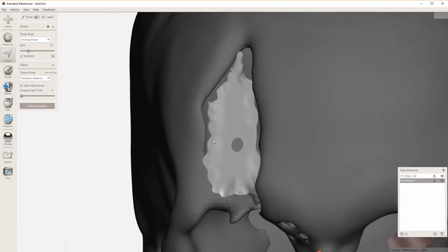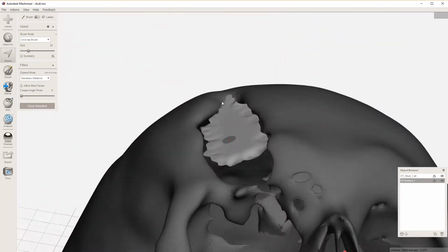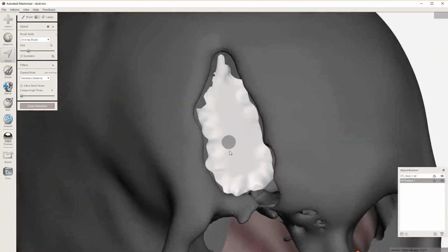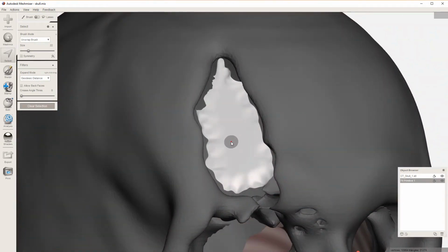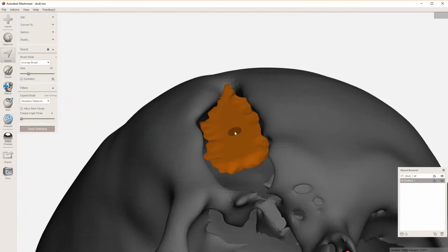This looks pretty darn good. Not good enough for surgical uses, but this is the next step. This is an infinitely flat plane, as you can see. We don't want that. We want this to actually have volume. I'm going to double click on this to select the entire thing and hit the D key for extrude. Or you can go up here and say Extrude, D.